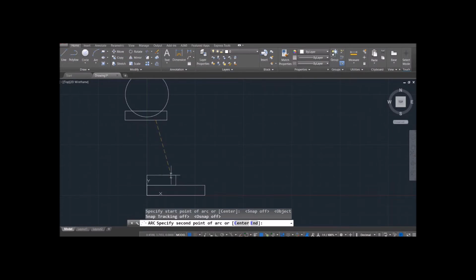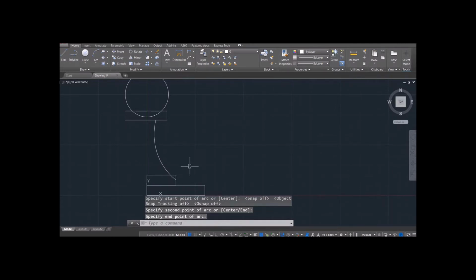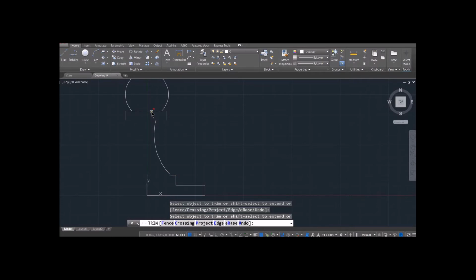For this arc, when you're connecting objects, sometimes it's good to actually overlap it a little bit and then trim it away, and then you're sure that those corners come together. For the trim command, enter selects all. Make sure you select all. Otherwise, you have to define cutting planes, and it's a real pain. Actually, the new trim command is a big improvement on this new version of CAD than what it used to be. So be happy that the trim command has that little select all option for you.